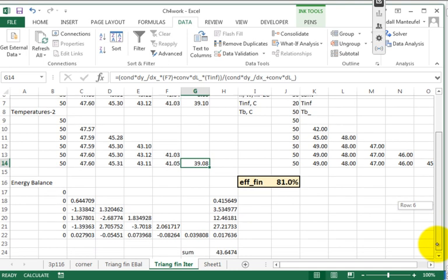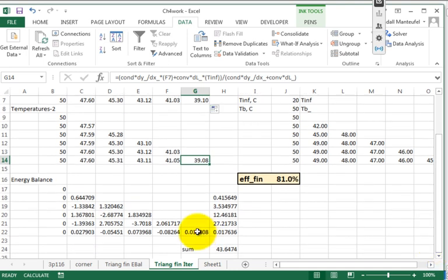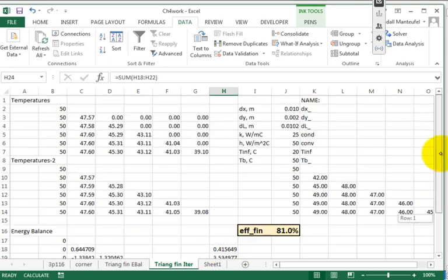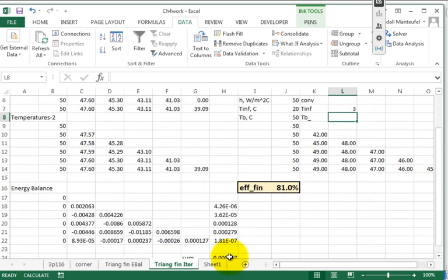And then you could come down and take a look. Does my energy balance equation look good? Well, it looks pretty good on a lot of nodes. But I'd even like that number to be smaller. So what we can do is go back and actually all I have to do is hit somewhere, put a number, and it'll do another 1,000. Just sort of because I already started. If I want to go back and start it at my original value, I have to copy that matrix up and do it again. And then let's take a look. It did another 1,000. It's even closer, isn't it?